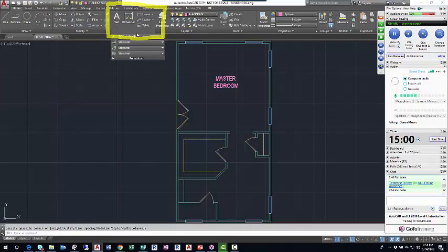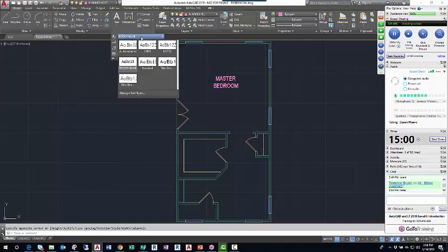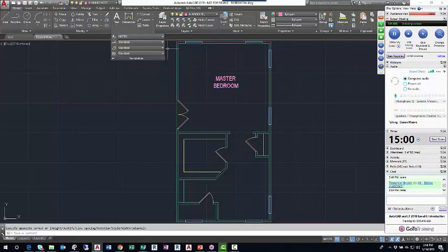Opening up the annotation panel, I gotta get rid of that highlight, it's blocking us. Erase. Right. Open the annotation panel, and then here's the current text style. Text style is room name. I'm done with room name. I want to use notes. I open up room name, and I click, whoops, missed it. Click notes. Now notes is my current text style.